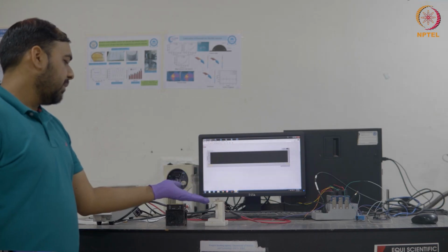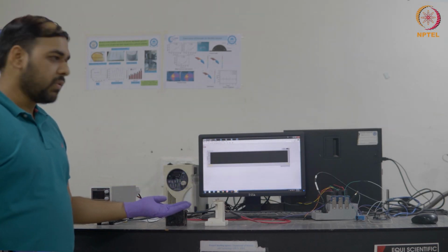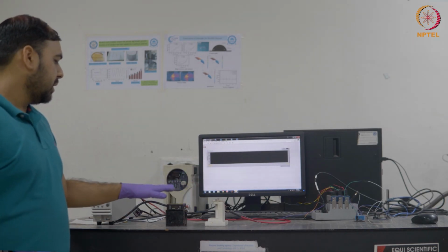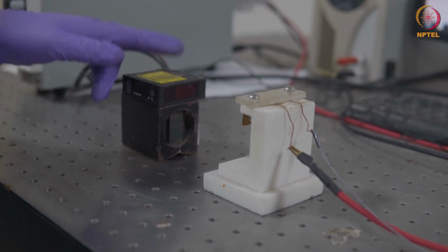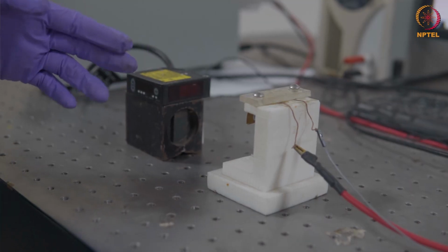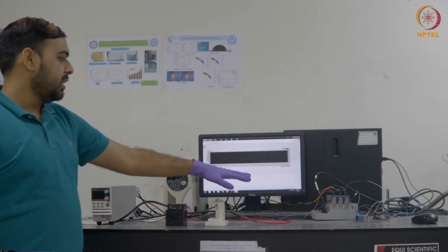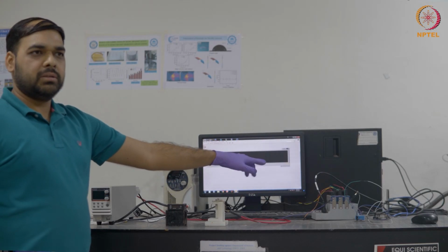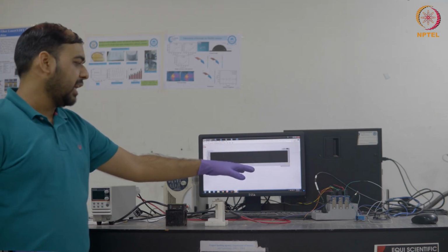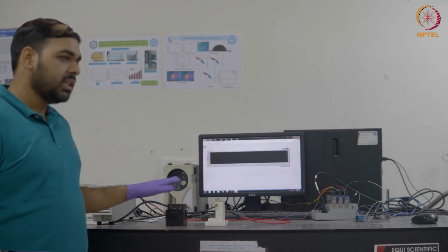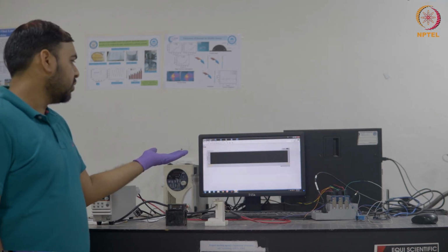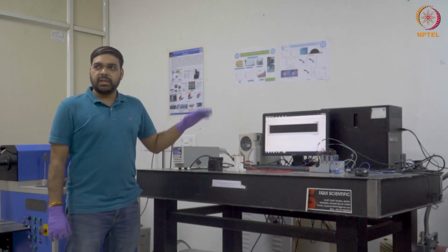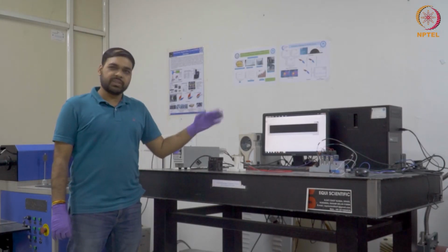As we supply the power, the bimorph will actuate in the forward direction, and that actuation is captured with the help of a laser displacement sensor. The input to the laser displacement sensor is recorded using a data acquisition, or DAQ, unit, which will convert this laser displacement data into recordable data that can be displayed in LabVIEW software in graphical form. Then that graphical form can be used for further studies.